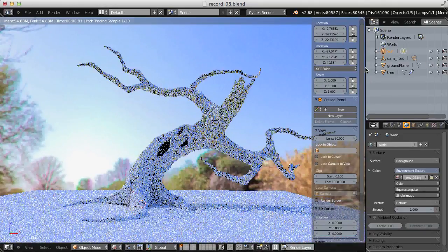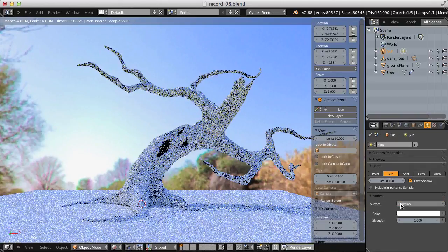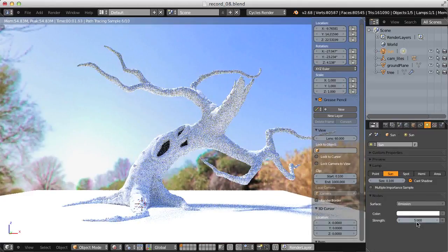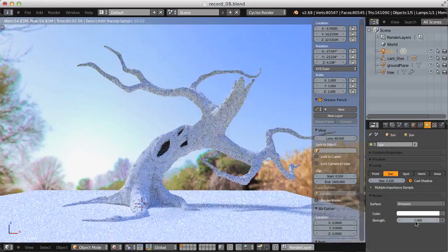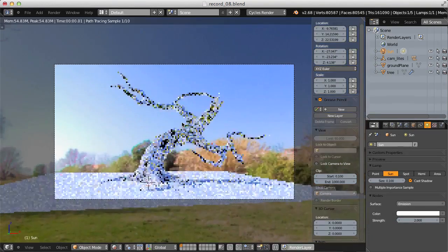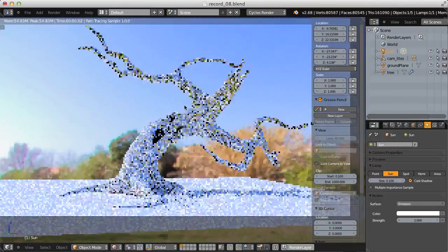But perhaps I can turn the sun power a little bit up. But since I created the lamp in the Blender internal engine, I need to click Use Nodes and change the strength from 1 to, let's go to maybe not 5, how about 2? Yeah, I think that'll work fine. And hit 0 to go back into the camera. What was I doing? Oh yeah, testing the displacement.